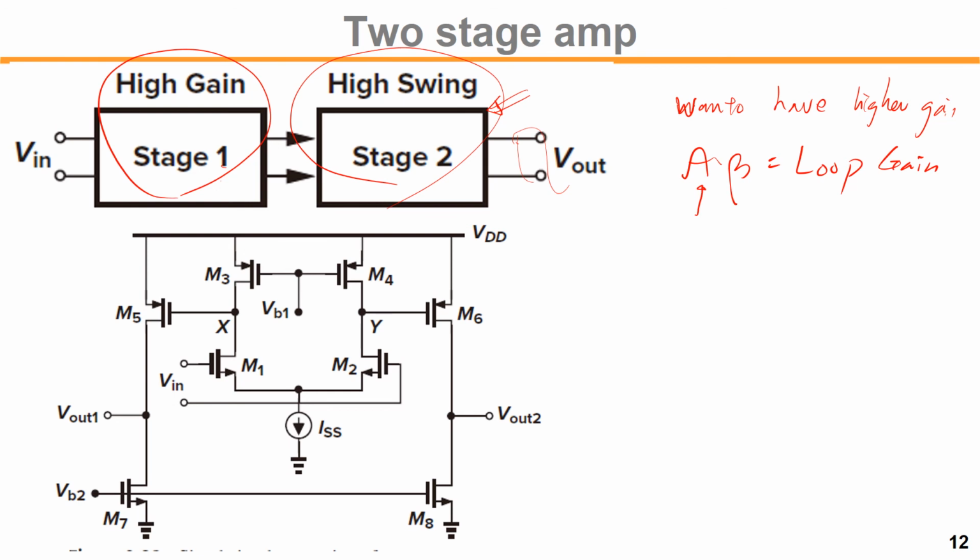So for example, here in the first stage, just the common differential amplifier with current mirror active load like that, and then we have an additional common source amplifier, right? CS stage there to get the large amplification range. What is the output range?